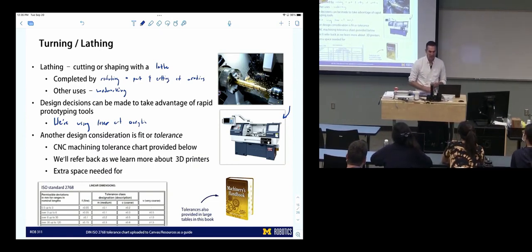My guess is that you would be at kind of tenths of millimeters. So you might need between 1 and 2 tenths of millimeters on the radius to give it the ability to spin more freely. So another design consideration is something called tolerancing.